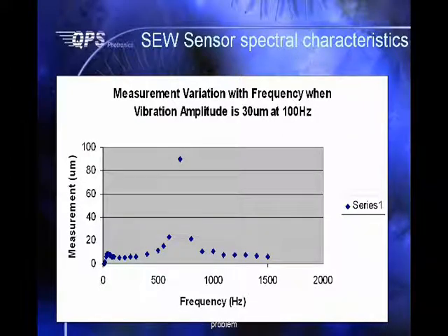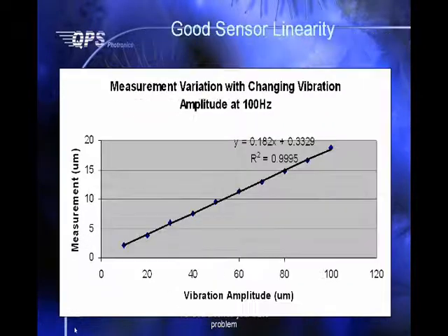Since our operating point is around 100 to 120 Hertz, we are working in this flat region. In case you are interested in higher frequency signals indicating some other problem, we can move this resonance all the way to 1000, and that is quite easy.